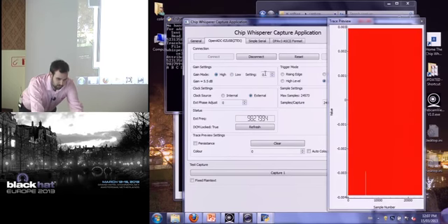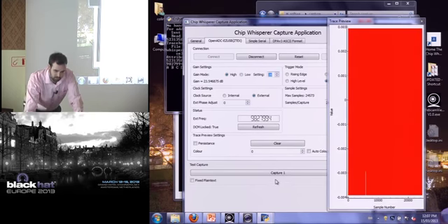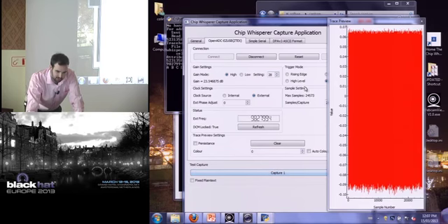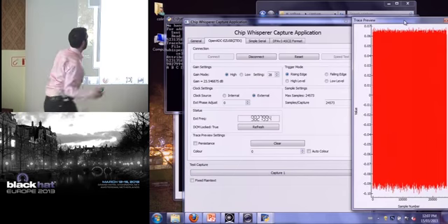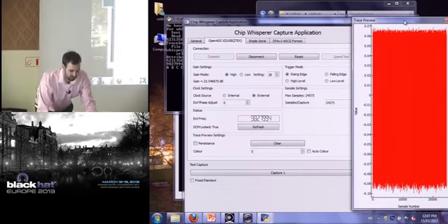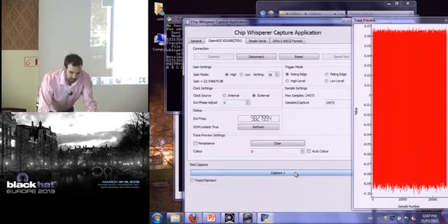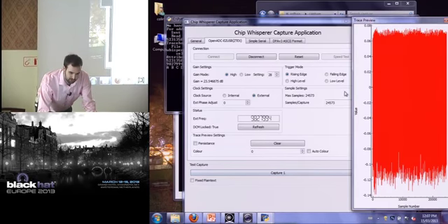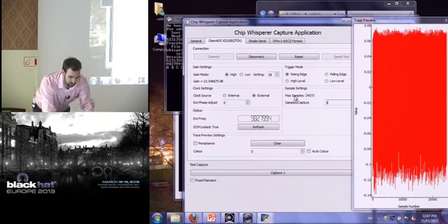Increase the gain. And you can start to see some signature there. So I'm going to set the trigger mode. The trigger is what I said before. I have a pin that goes high right before the encryption happens. So I always want to synchronize to that rising edge. And I'll reduce how much data you have on screen here.